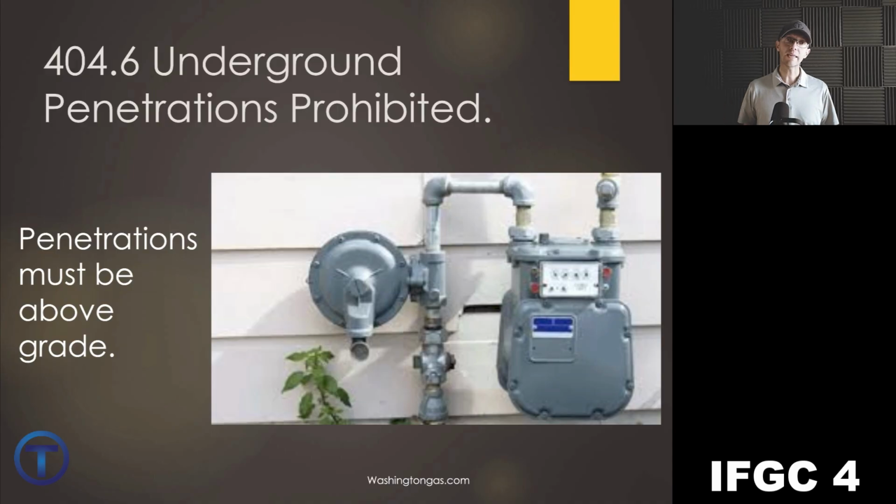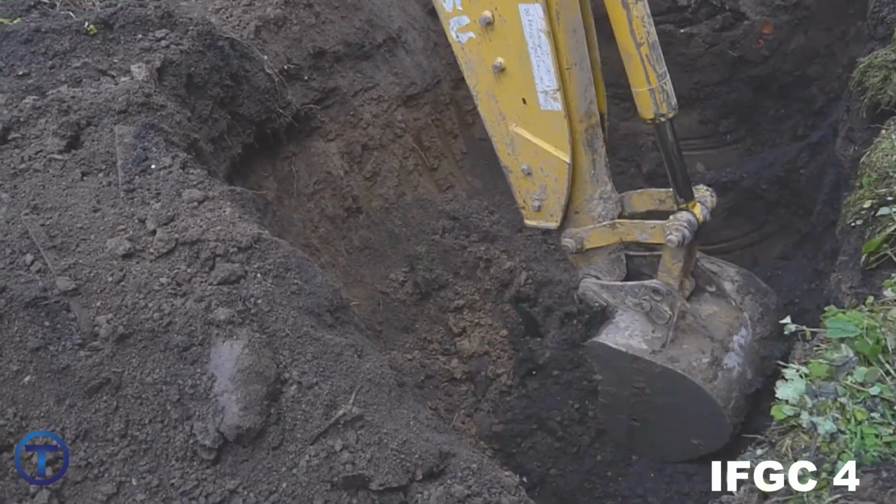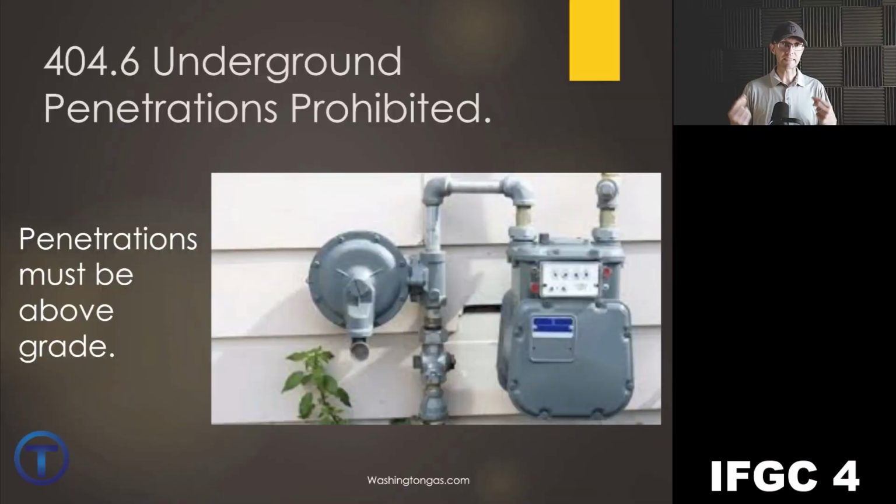404.6 talks about running that gas pipe into the building. We've got to get gas into the building. Water lines, sewer, we just go below. We can come through the dirt, through the side, or underneath, no problem. But gas is different. All building penetrations have to be above ground.